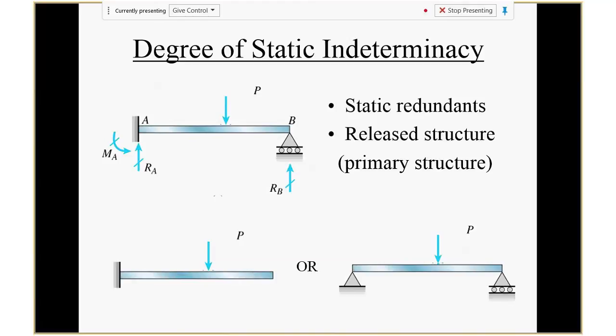For example, it's shown here, right? If you have this beam at the top, that's the indeterminate we just said, right? So the degree of indeterminacy is 1. Therefore, we just need to remove 1 additional load. Then it becomes a determinate structure. Actually, there are multiple ways you can do that. For example, on the left, it's showing remove this restriction. So you replace it with a reaction force, let's say called RB here. You say, I don't know RB. Yes, we don't know, but it's a load, right?